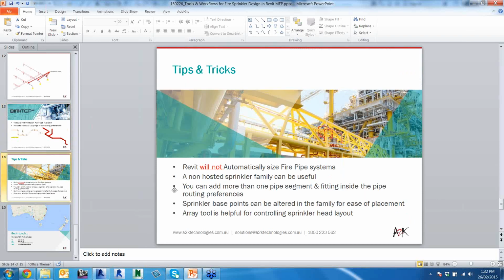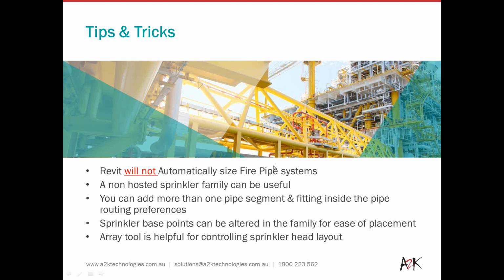And the last slide that I wanted to show you, just to recap, was some of the tips and tricks that we went through. Just keep in mind that Revit will not automatically size the fire pipe system, so the auto pipe duct and pipe size tool unfortunately doesn't work with the fire pipe systems. But we went through some effective ways of how you could size those.